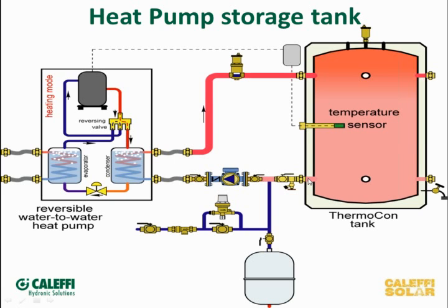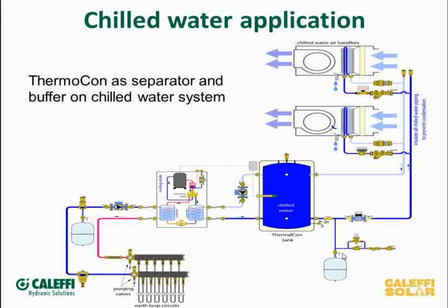One of the things that the Geo people have been screaming for years is, give us some tanks with some big port connections and well insulated, so if we're going to run this as a chilled water application, we don't have to worry about sweating and stuff on the tank. So we recently addressed that market. We came out with a tank that would work either in the heating application that you've seen there, or the same thing applies to a chilled water application.